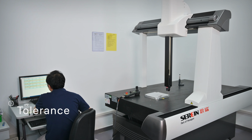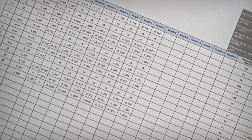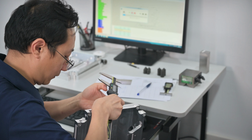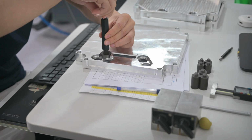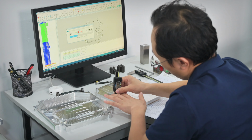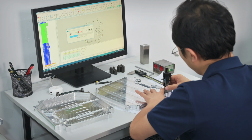The third part is the part tolerance and precision. Don't underestimate those tiny numbers on the drawing. They play a huge role in determining the cost of machining. The higher the precision, the higher the scrap rate. So, when setting the part's tolerance, designers must consider the actual requirements of the part, not just chase after tighter tolerance for no reason.